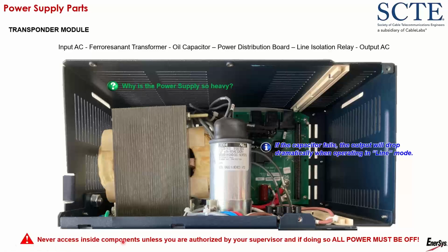I have a note down here. Don't access the components inside the power supply unless you are authorized by your supervisor. And if you are accessing anything inside of here, like I have it open, always have all power off to the power supply. Never have the power on when you're accessing anything inside of it.